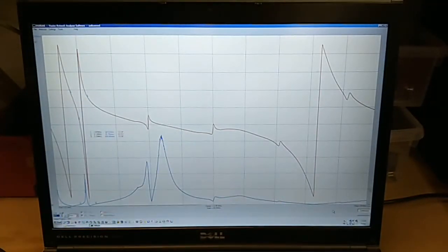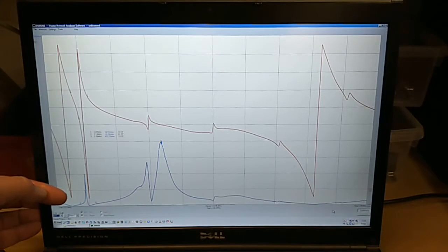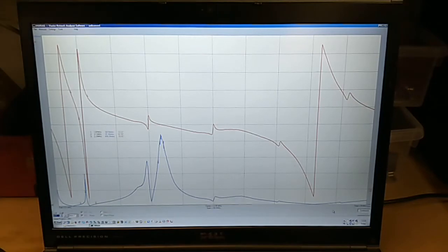So as before, this frequency here, if we just have a look at what frequency that's actually at, take it right down there, it's obviously a very low impedance series resonance at 1.22 megahertz, and that is predominantly about those series tank capacitors.